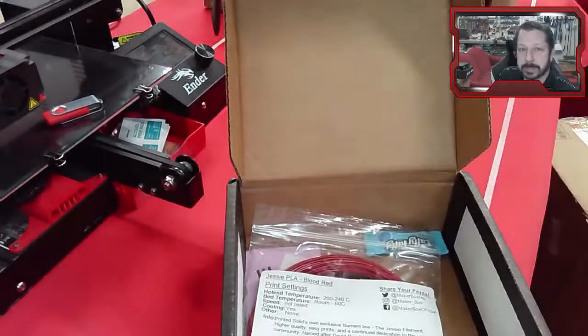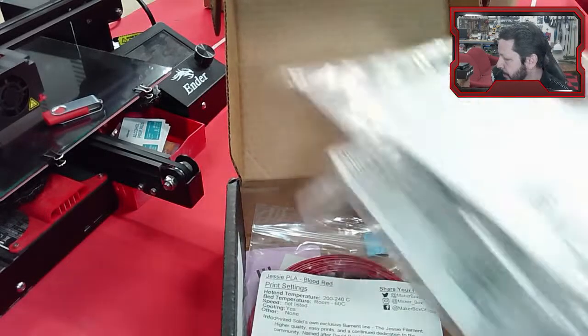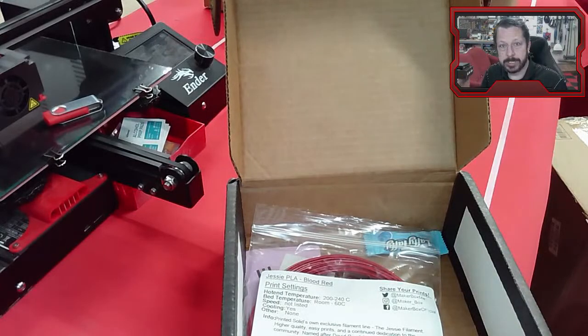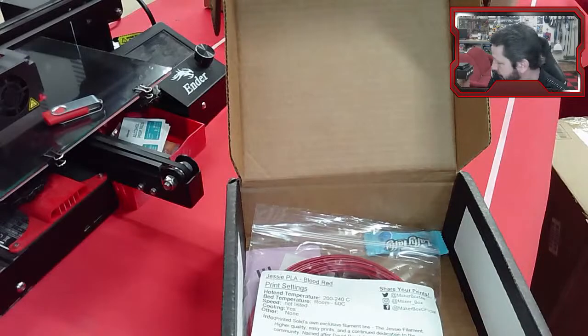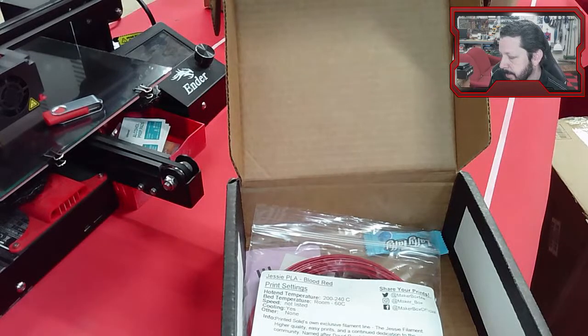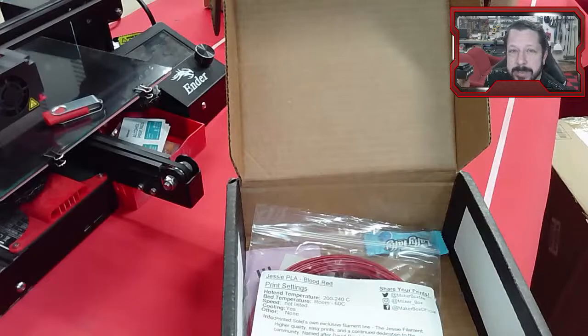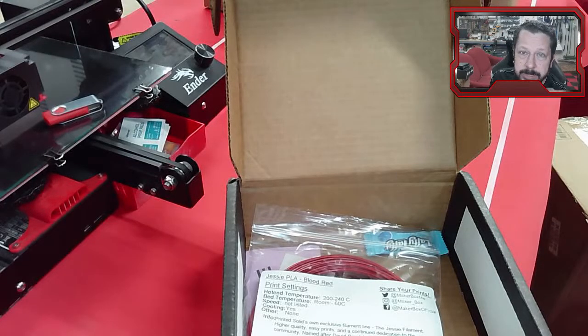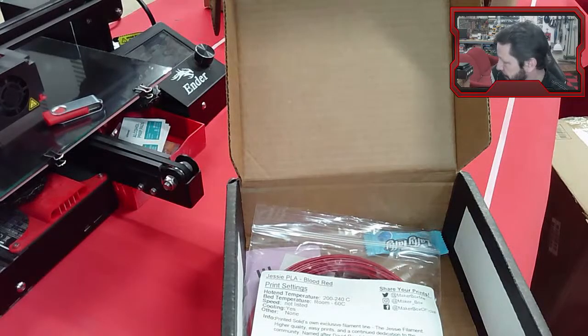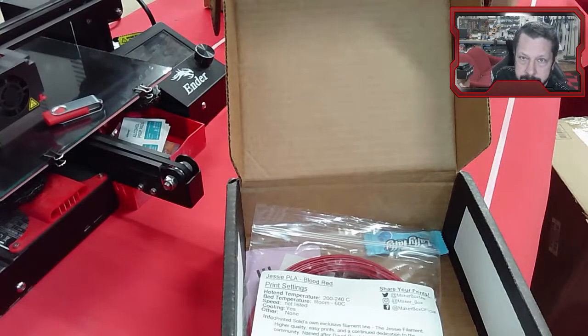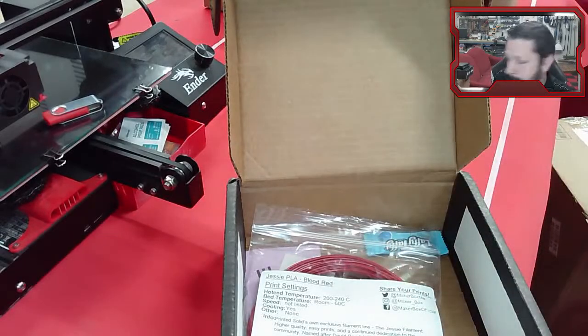So some materials, not PLA, but some materials need the printer itself to be enclosed in a box so that the whole environment that it's printing in is kind of hot. And so if you see filament that needs that, then unless you're willing to build some kind of box around your printer, it won't print as well as it could. ABS is one filament like that that's pretty common, but kind of needs an enclosed chamber to print. You can build them. Some people just throw a garbage bag over the printer and now it's enclosed, and they use the heated bed to heat the chamber.